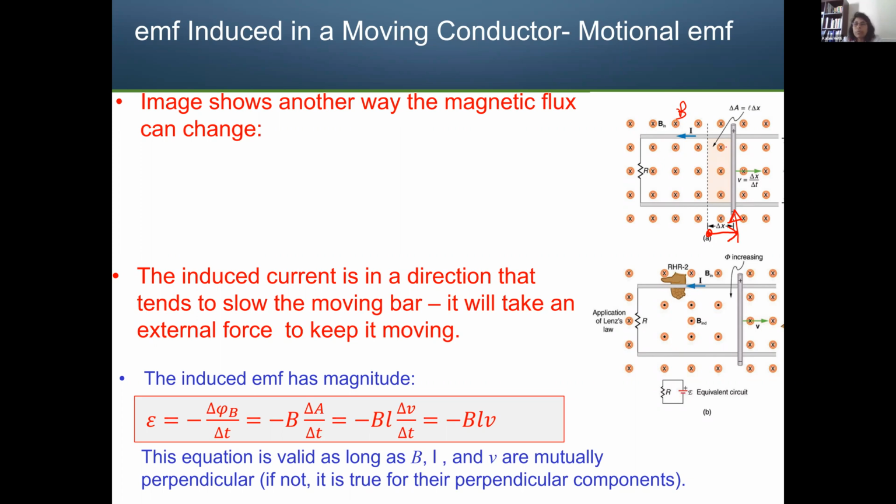Right side is open. Left side you have a closed loop. This is your closed loop that you are creating. It was here earlier. Now I have a larger cross-sectional area, right? So now what you need to think is, you have a larger cross-sectional area. That means flux is BA. You don't change the cosine or B or anything. What you are changing is you increase this one, right? So because of that, flux will increase.